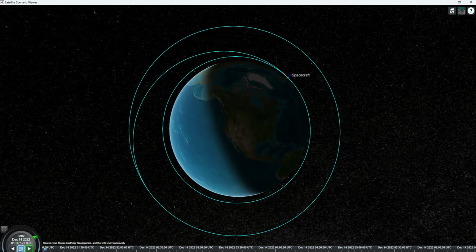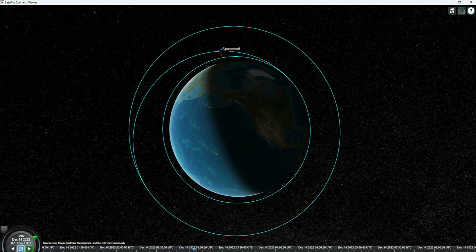As we can see here, the satellite first starts by completing a full orbit at the lower altitude. It then points in the maneuver direction and raises the orbit to enter the transfer orbit, completes half the transfer orbit, points in the second maneuver direction computed, and performs the last maneuver to complete the Hohmann transfer.